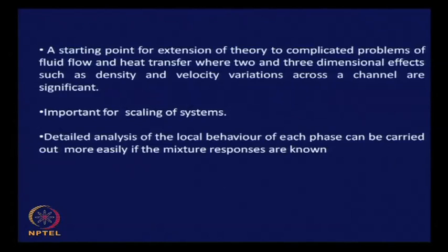Naturally, when it has got so much versatility, it is quite natural that it is very important and very useful for scaling of systems. Suppose we have performed experiments in a small scale, in a pilot plant scale in the laboratories, and we would like to scale it up for industrial scales. If we have some way of accounting for the 2 dimensional, 3 dimensional effects, if we know how alpha can be related with J21, and we know that J21 depends upon the fluid particle interactions rather than the fluid wall interactions, then in those particular cases the scaling up becomes very important. This is one more thing.